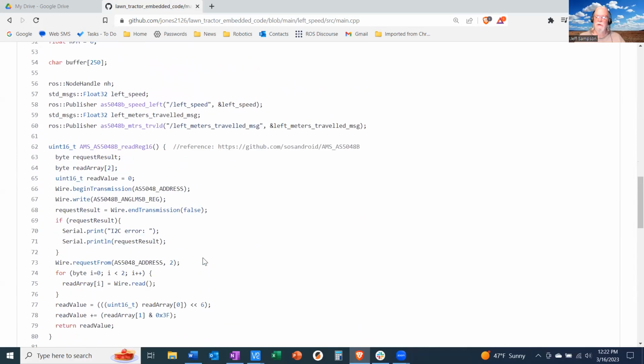And he doesn't have to ensure his back wheels are going at the same speed, because since we're running Ackerman, he's got the engine and a differential, so it automatically knows how fast to make the wheels go depending what direction you're pointed. And if you're thinking about the fact you have differential drive, you may have to control the speed of the two to get it to go straight. I think that was your question.